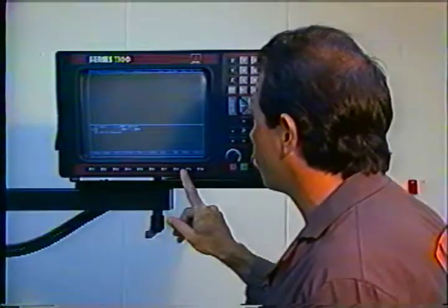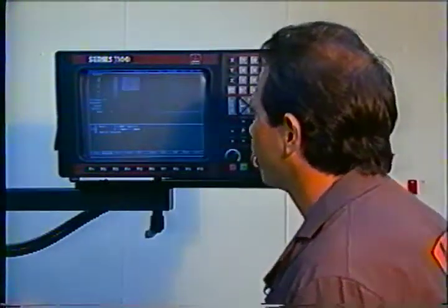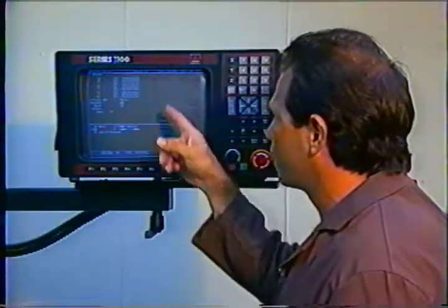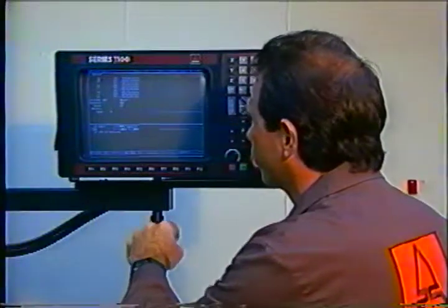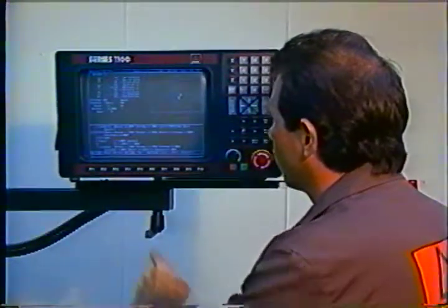From the main edit menu, F2 is Draw Graphics. When I press that, the draw screen comes up, and I'll just press the Run key. Okay. Now I'll turn the tool display on so we can see the tool drilling the bolt hole circle now. This is an isometric view, so it's a view from our perspective here on the right side of the machine. Okay, I can see now that tool 2 is active and it's coming in to do the circular pocket now.